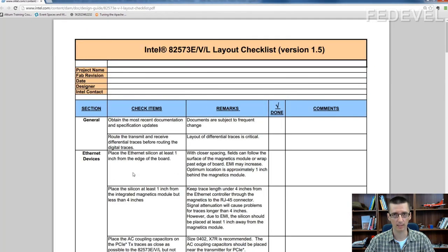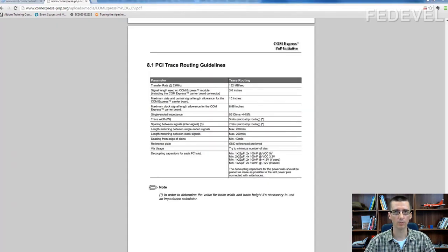Again, what I wanted to say with this, if you are not sure how to length match a particular interface, then most of the time it is correct to just make the signals in the interface exactly the same length and it will work. What to do with the slow buses, parallel buses? How to length match these signals? I use this kind of recommendations here.